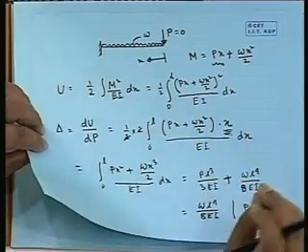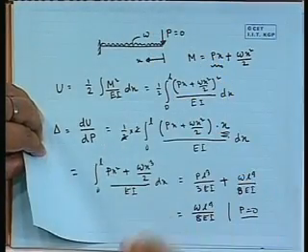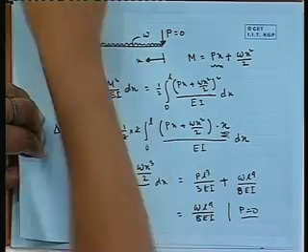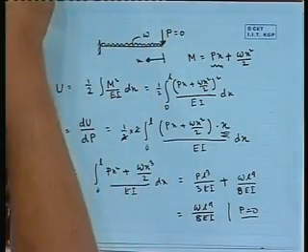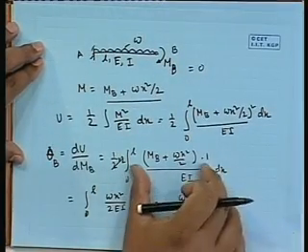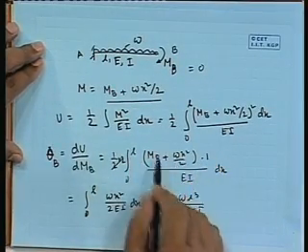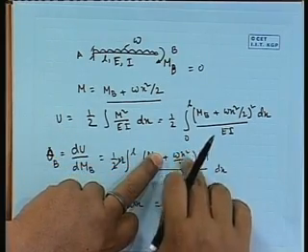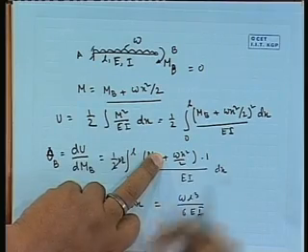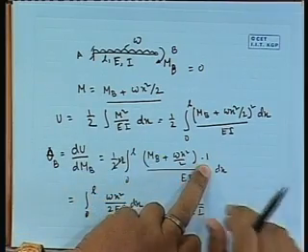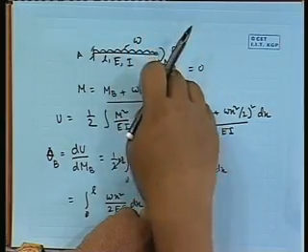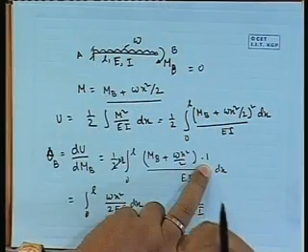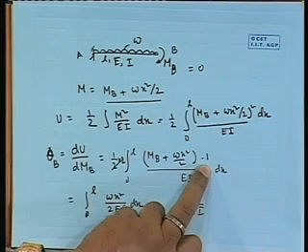So, this small m is due to the unit load applied at the free end where we want to get the deflection, or in that case a slope calculation. If you come to that level, this part is the bending moment where M_B is equal to 0. So, this is basically the expression for capital M, the moment generated by the actual load. And this is the moment if we put 1 unit moment. Anywhere the moment will be 1 unit, so it will be 1. So, small m is the moment generated by 1 unit moment at the free end where we want to get the rotation.